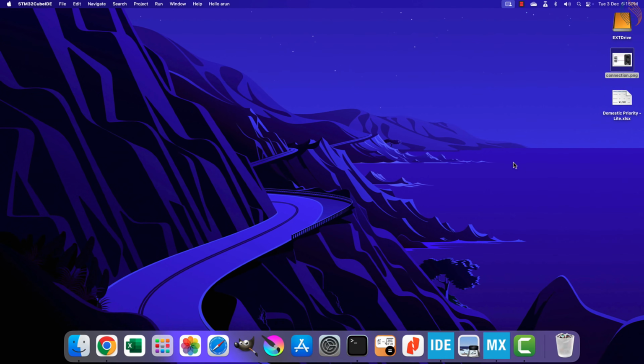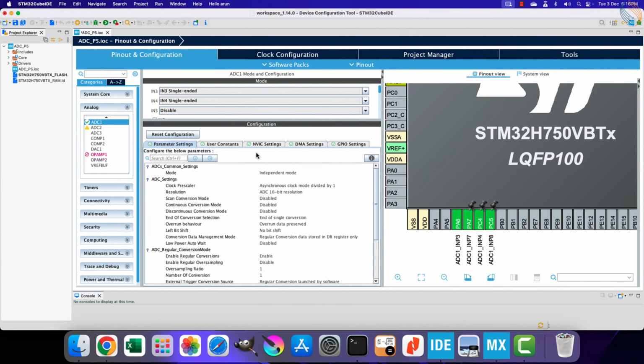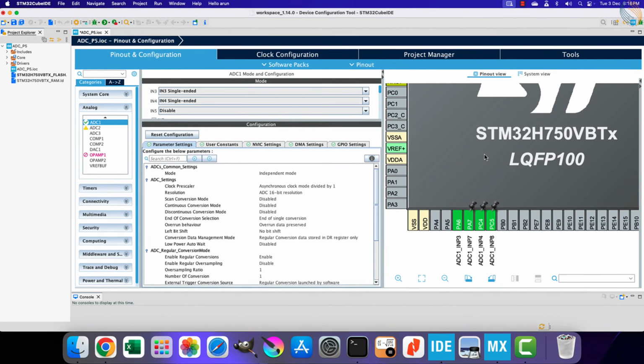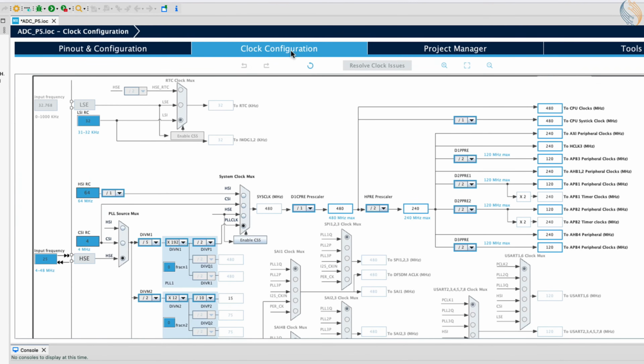while using the Cortex-M7 based MCU. Although there is no reason for us to not use the DMA while reading multiple channels, since there are ways to do it, we will cover them. We will first use the method of discontinuous conversion mode to read one channel at a time. Later we will modify the pre-generated code itself, so that we can read any random channel at any point in our code.